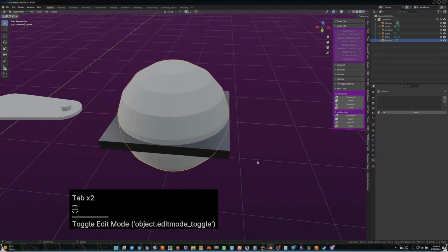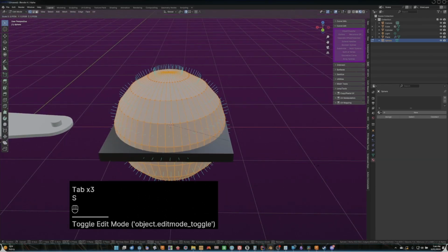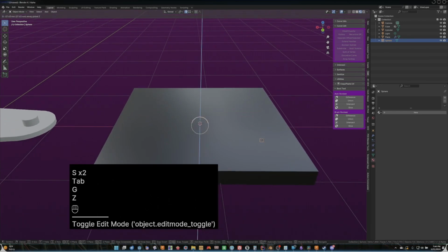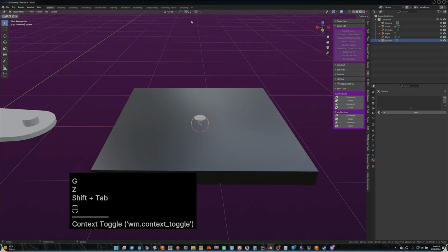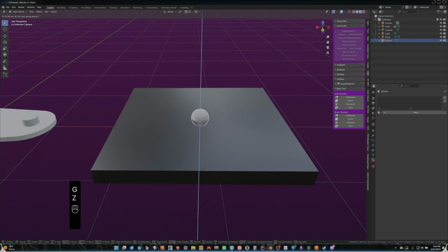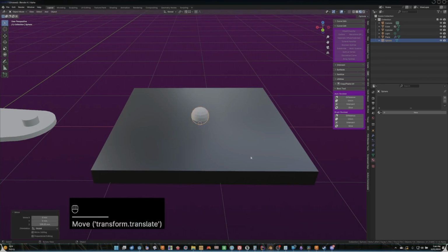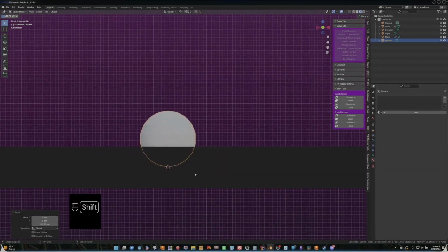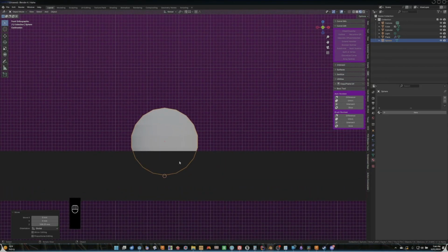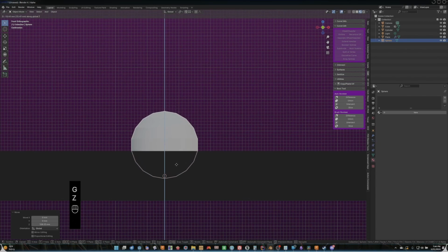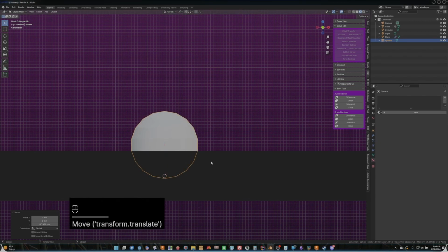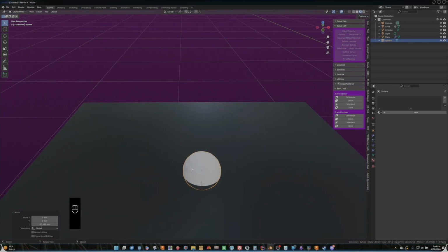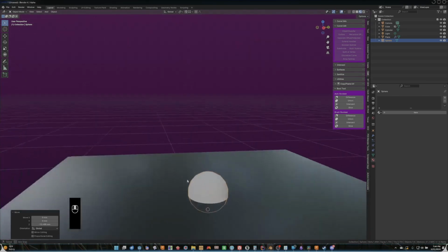Yeah. Okay, so now I'm just going to go into edit mode, scale it down some more, and I'll bring it up. I'm going to turn off the vertex snapping, bring it up on Z. And I want to make sure that I'm not over the median line for this. So I'm just going to bring it down to right there because I don't want to have a ring, like a collet around it. I just want to have the cone effect, the dimple.